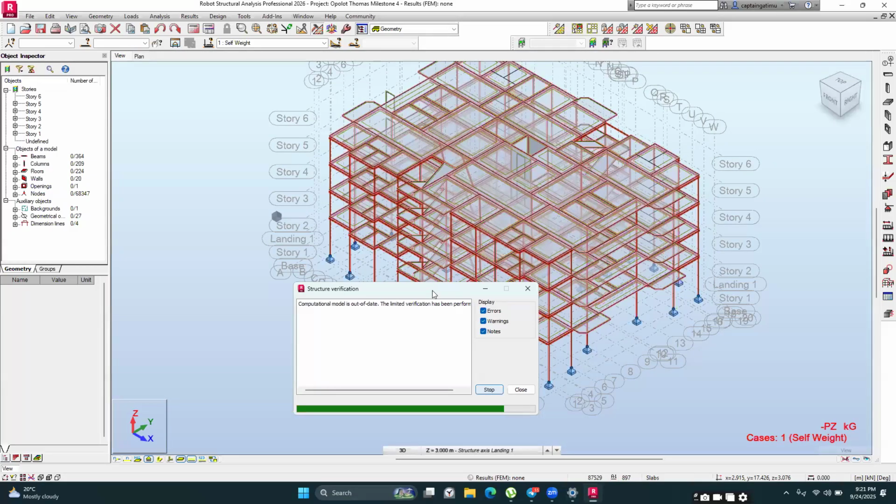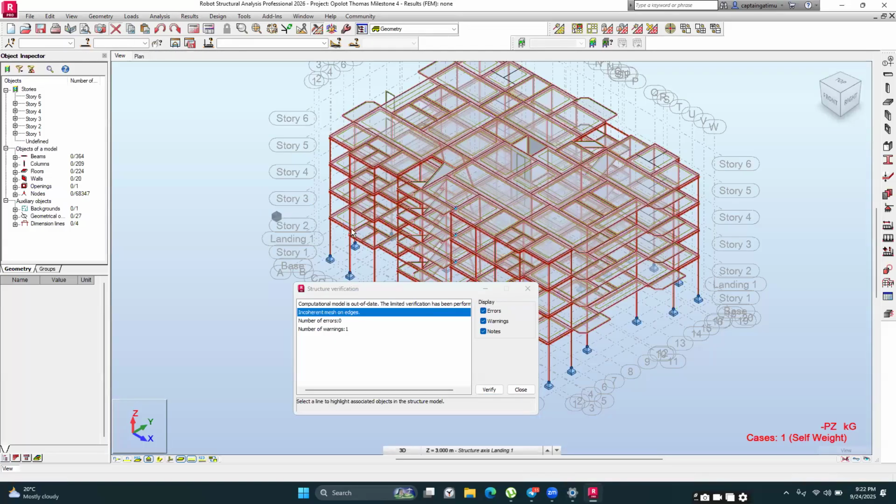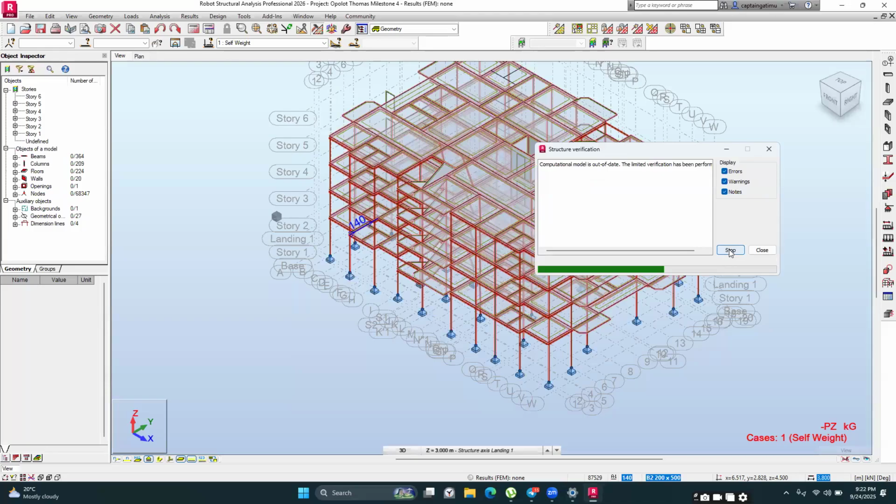So you have to do a couple of iterations, especially with the small elements. They're usually due to very, very small inaccuracies as you model. So that happens, and if they're insignificant, then you can delete some of them. But if they appear as you do the meshing on the single floor slab that you had, then it's advisable you just correct them from there. But if they're small, you can just delete them.